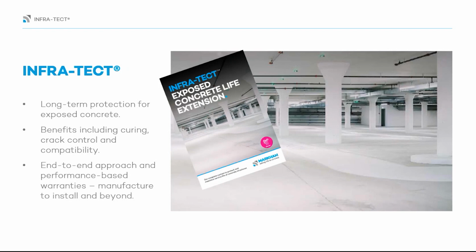I think it looks better too, just having that natural concrete finish rather than like a coating over the top. Coating over the top increases maintenance, having to reapply paints, etc., to keep the aesthetic appeal to a standard. So by having the concrete treated in its natural form and allowing it to do its job and perform as it's intended without having to have a topical coating over the top can save time and money along that construction timeline as well.